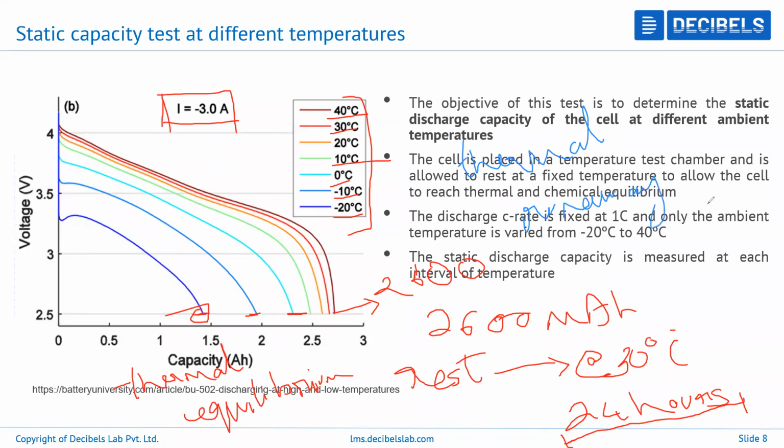Thermal runaway is basically a phenomenon where the cell or the battery pack starts to overheat, and it heats up to such an extent that it's not able to give out the heat at a sufficiently high rate to maintain a steady and stable temperature. As the battery gathers more and more heat, the reactions inside the cell build up even more, and because of this, at some point your cell can catch fire. That process is called thermal runaway. That is why it is always preferred to keep the cell at a maximum of 35 to 40 degrees Celsius and not more than that.